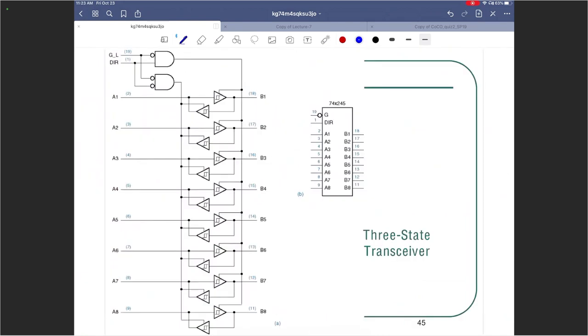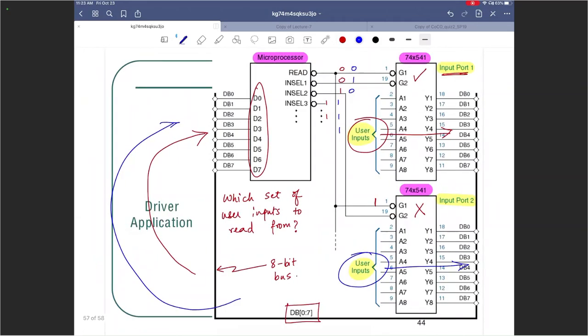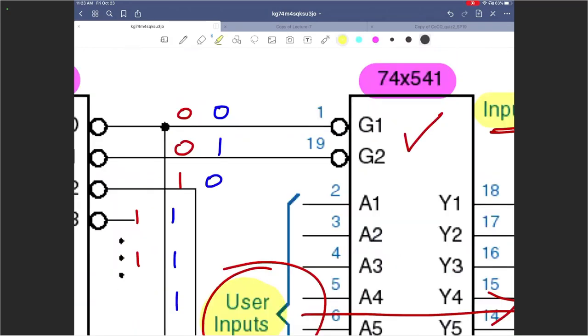Let's see, what is the point in putting a NOT in front of the enable for the 74X? Do you mean this? Okay, so wherever you see a NOT, it has to do with the designer preferring an active low input. Now, it could be for many different reasons.